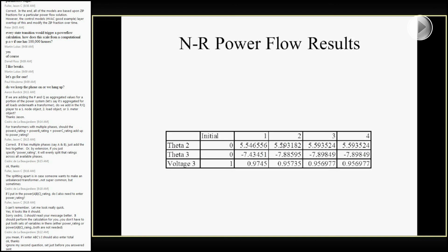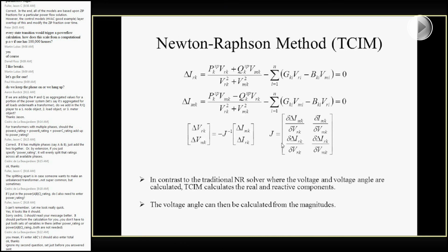The one we actually implement inside GridLAB-D is a slight variation on the Newton-Raphson method called the Newton-Raphson current injection method. And rather than using power injections, it actually changes it to be very similar to how the backward-forward sweep algorithm works and changes them into current injections. You're still updating your voltage values. It's not the angle and the magnitude anymore.